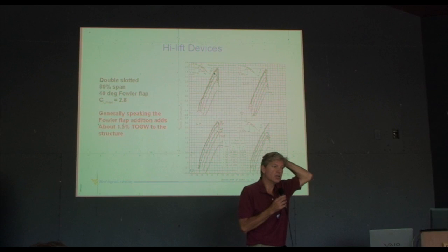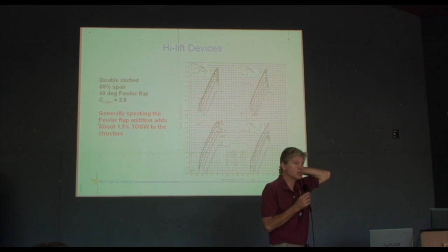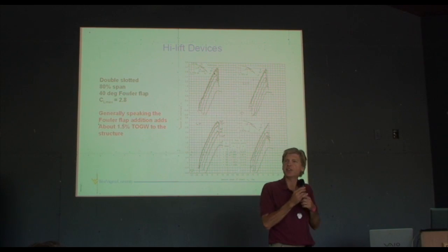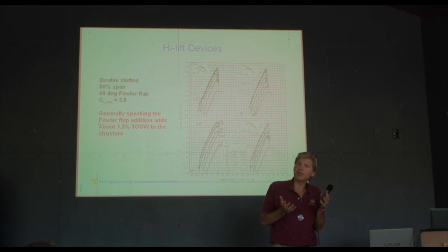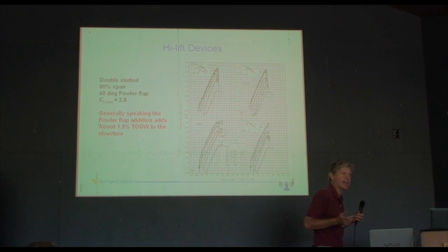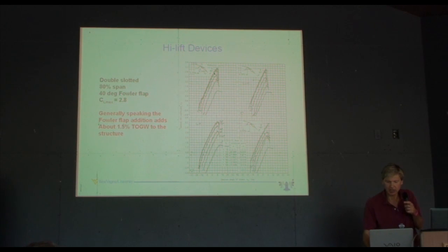Also, while the area goes down, because the span is longer, the spar will get heavier. Right, because of the increased bending moment. So I figured it would wash back and forth, and it would all probably wash out, or if anything there would be a net benefit when you're all done. In the worst case scenario, it would come out even. So I didn't spend a lot of time addressing all that.